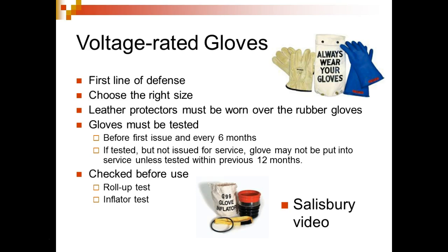It was really interesting: they'd have a big old water vat, fill the gloves up with water, dip them in there, put electrodes between the two, and measure the current flow through the glove. If it didn't meet a certain standard, they would reject them and throw them away. So you're supposed to check these things every 6 months. If tested but not issued for service, gloves may not be put into service unless tested within the previous 6 months.